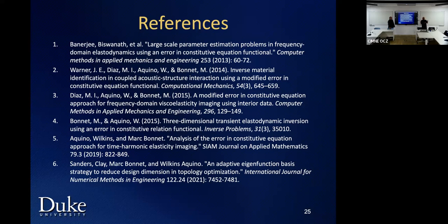Basically, an L-curve type of idea is you plot the L2 functional and the error in the constitutive equation functional, for solutions of the inverse problem. You choose kappa for different kappas, solve the inverse problem many times, and this gives you an L-shaped curve. You choose the one closest to the origin, because this is the place where you have this balance of the two errors, heuristically.